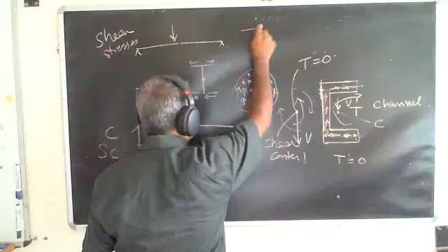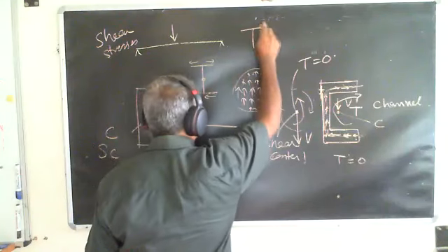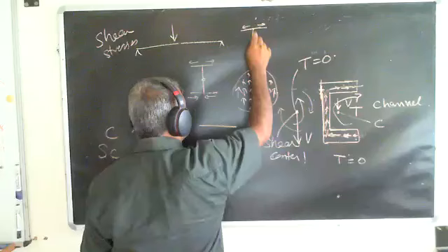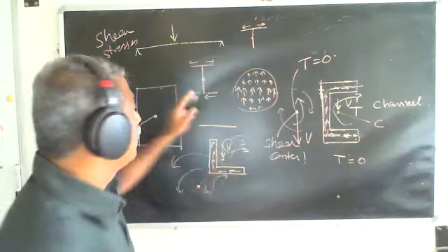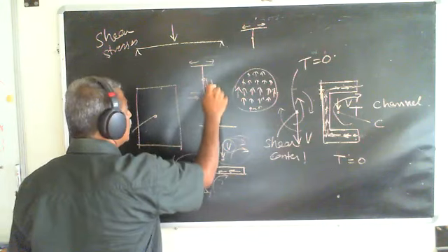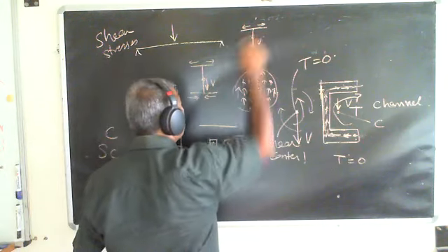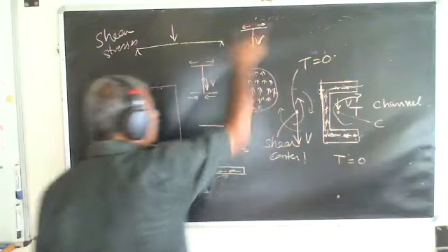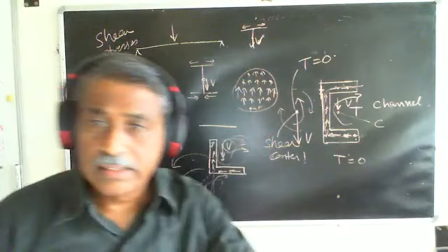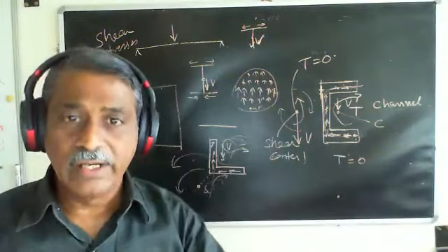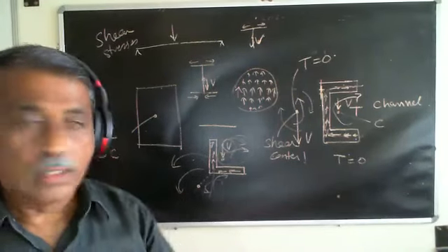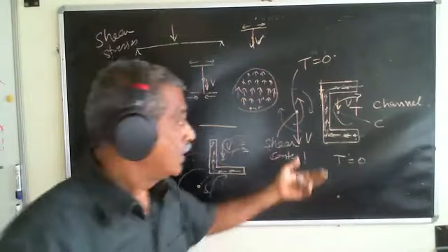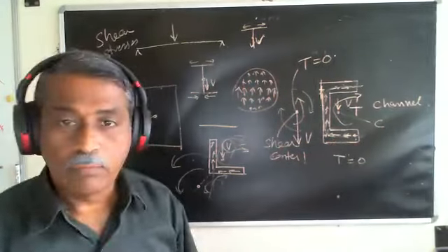It's the same thing with T section, right? One is like this, the other is like this. So if I take a point which is the centroid, it happens to be the same. So I can apply the shear in this direction, right? So any symmetric cross section, the shear center is going to coincide with the centroid. If it is not a symmetric cross section, then I have to be worried about what it is.